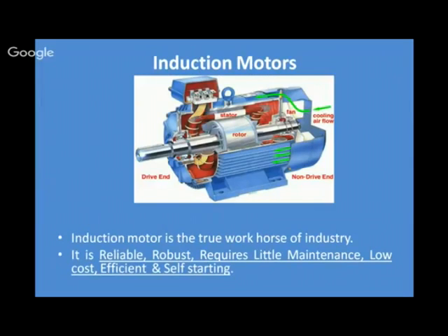So here we are considering only the induction motor. Why are we using the induction motor here? Because it is a very widely used motor. It is reliable, robust, and requires very little maintenance. It has high efficiency and it is self-starting, and doesn't require any special type of starting. So we will now see the various fault diagnosis methods for induction motors.